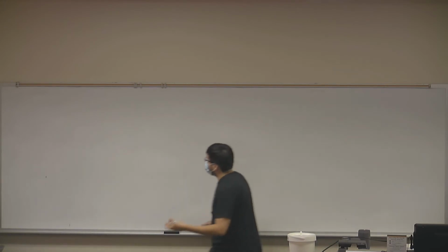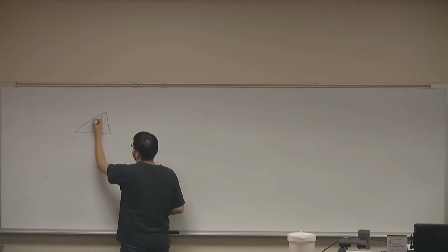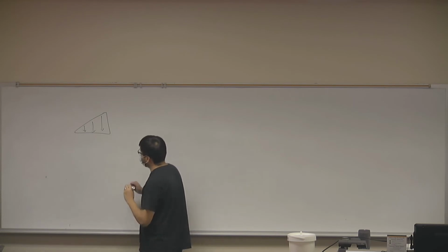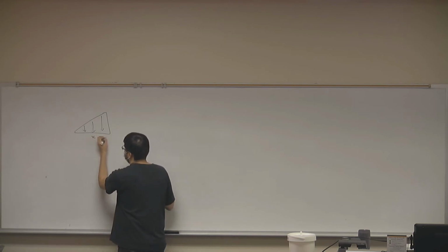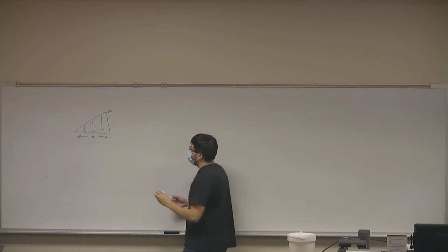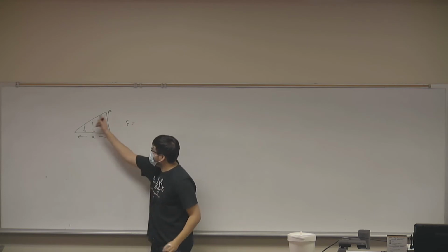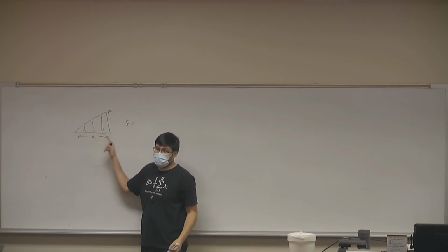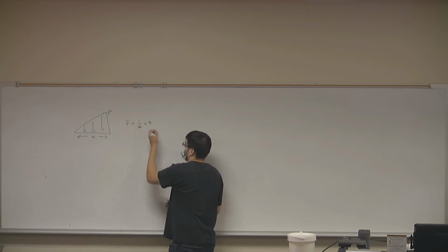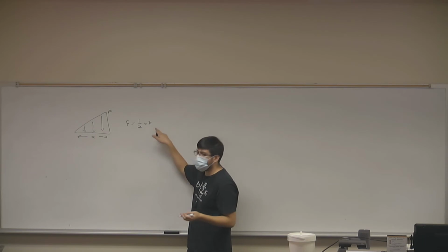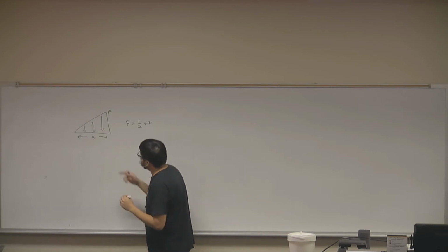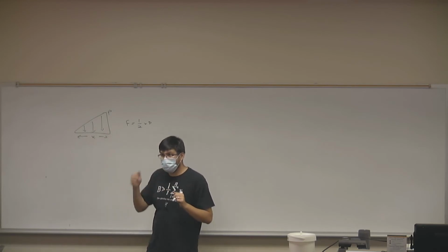Yeah. So we have this load, right? It's a triangular load. So we've reduced it into a force because we know this load is acting over a distance of x. It has a maximum value of, I'm just going to call it P. And we said that the force is equal to the area that this triangle forms. So the area of a triangle is 1/2 base times height. And that's what we did, right? 1/2, 1.5 times 80. Good. But now let's look at where that force acts. So the force acts, we said, on the centroid of this distribution.